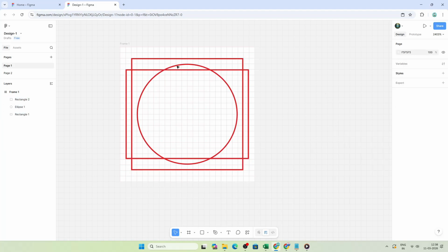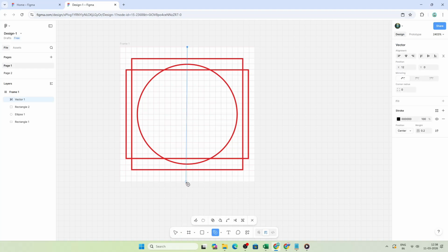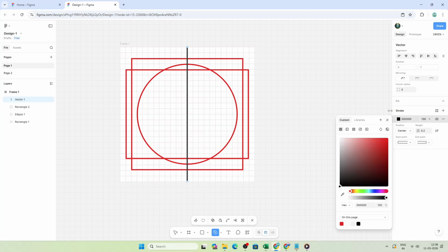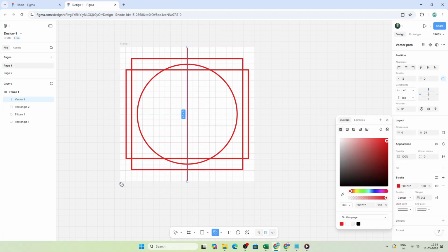Now move into drawing with intent. Switch to the pen tool by pressing P. As you plot points, hold Shift to constrain to straight lines or 45-degree angles for clean, repeatable geometry. Fewer, smarter points will produce smoother curves and make edits easier later.